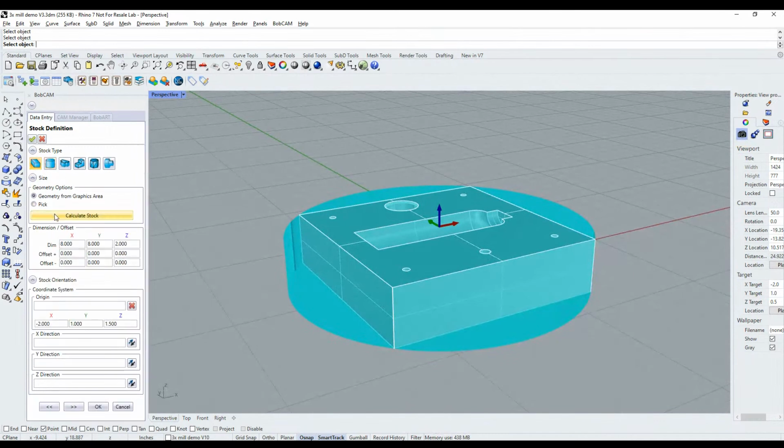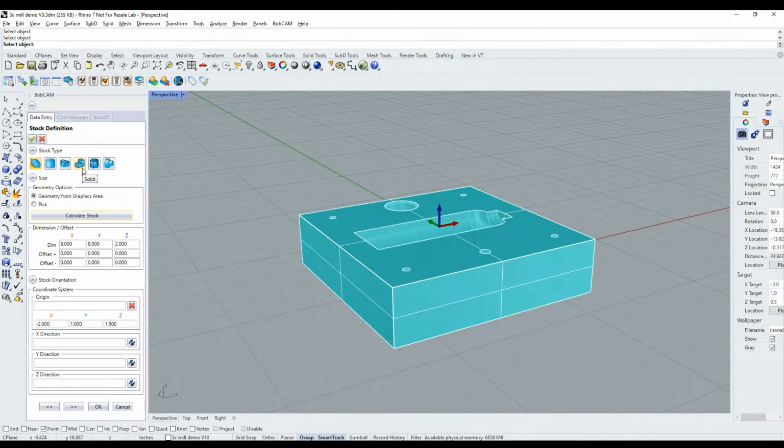If we want to extrude it from wireframe, select an existing solid model or STL model, or revolve a surface around to create a stock model here. And so we're just going to be using rectangular stock and drilling along a square shape like this.